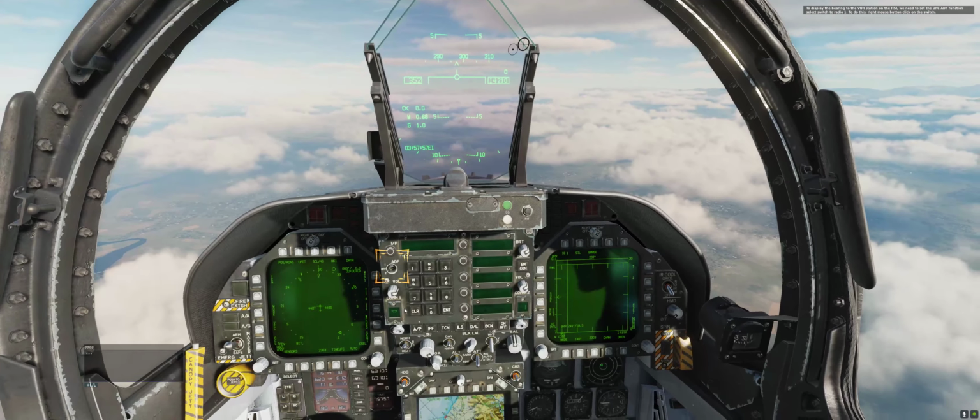Press spacebar when ready. In order to display all TACAN information on the HSI and HUD, press the TCN or TACAN push button on the HSI. Upon doing so, it will be boxed. Now we need to turn on the TACAN and set the code of the desired station. Press the TACAN button on the UFC.